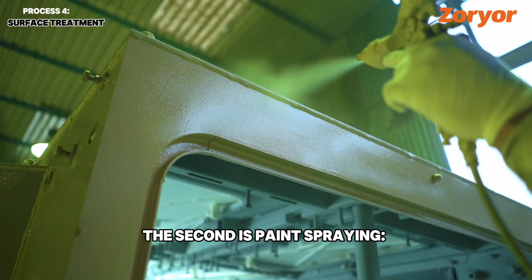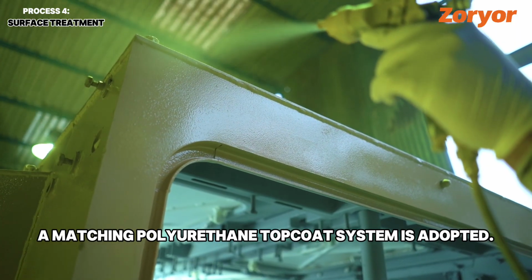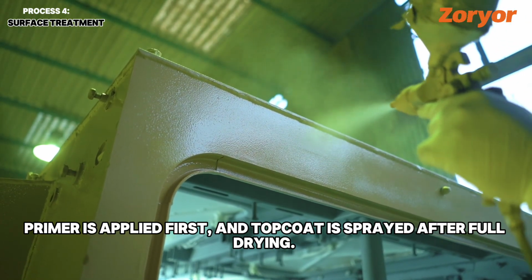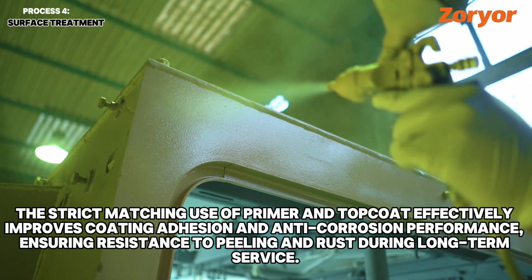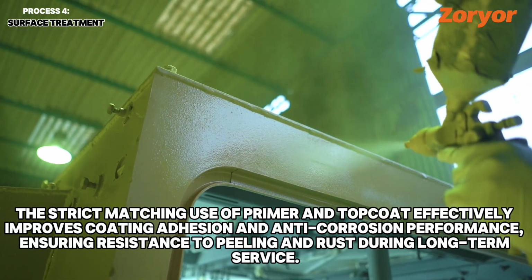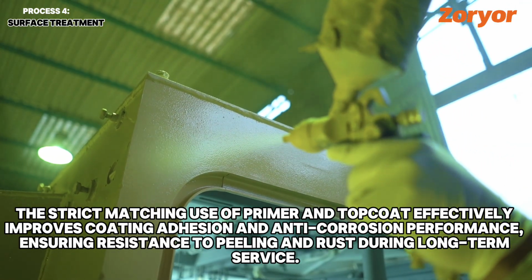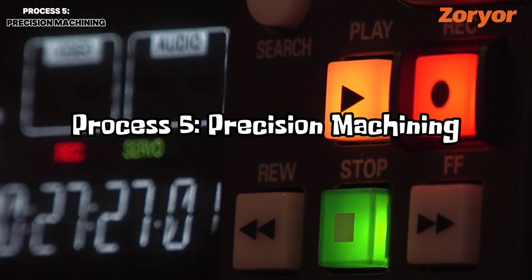The second is paint spraying. A matching polyurethane topcoat system is adopted. Primer is applied first, and topcoat is sprayed after full drying. The strict matching use of primer and topcoat effectively improves coating adhesion and anti-corrosion performance, ensuring resistance to peeling and rust during long-term service.